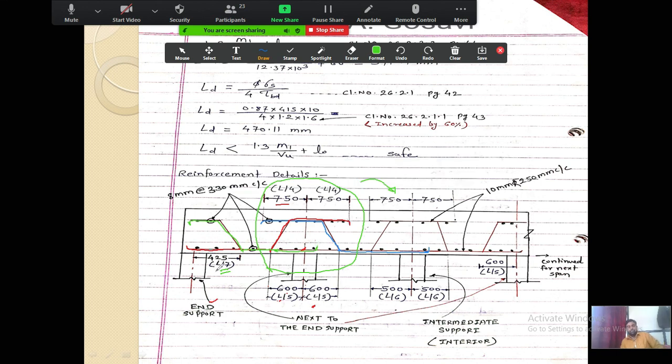And the same mirror diagram is over here, on top of this. Whatever dots you are seeing here are nothing but your distribution steel, in the other direction towards the width, parallel to the width, and this is along the length. This is the steel which is parallel to the length that I have shown over here.